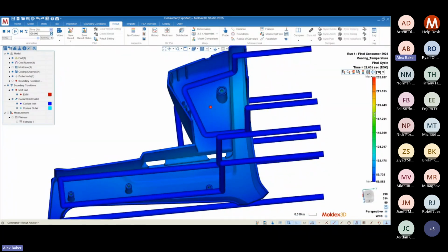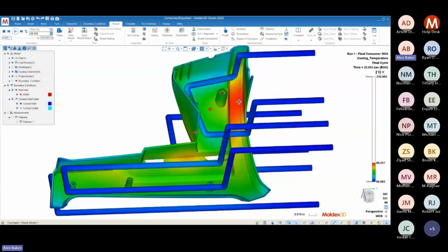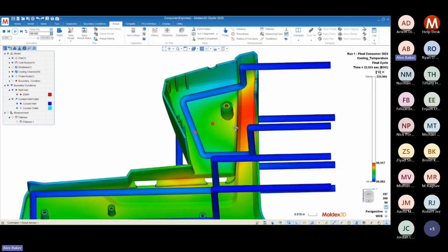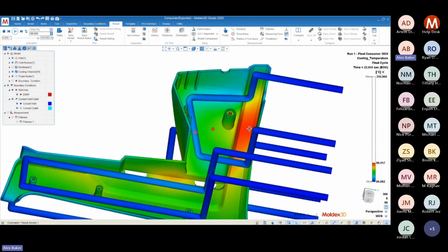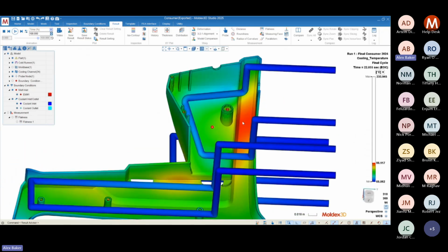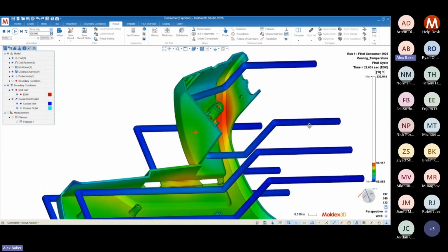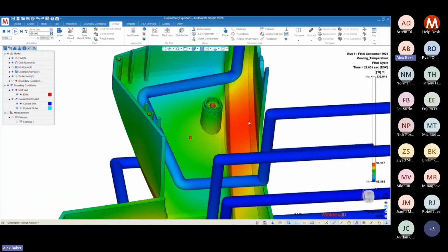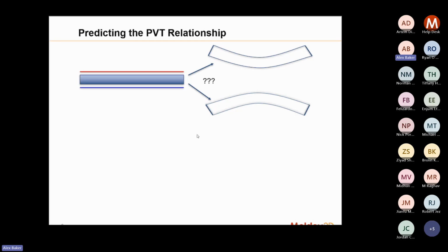What we can actually see, if I recreate that temperature distribution that we saw earlier, is that the heat accumulation happens between the inlet and outlet of this cooling channel going on the bottom side, which is interesting. You would almost think that the heat would be attracted to this cooling channel, but it is not. It is actually going to prefer, to personify it a little bit, to stay in the mold, and it will accumulate over a large number of cycles. This is going to create a hot spot in the mold, therefore a hot spot on the surface of the part, and therefore a differential temperature of the part that will apply similar to our example from our plaque.